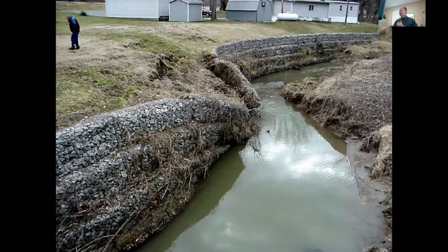like these rock gabions. These are wire baskets filled with rock and laced together. They're laced together and then filled with rock and then closed to make a rock wall. Well, this got undermined by the channel because now velocities underneath the gabion wall have caused the channel to erode so much that now the wall is leaning and failing.